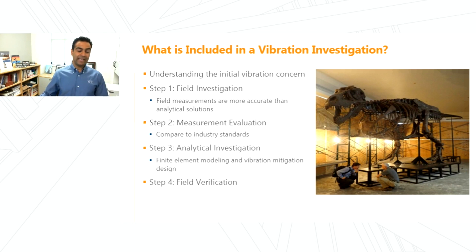And then finally, the field verification. As Rich described, this is not a strength problem. This is a serviceability problem. It's not well codified. So we usually try to do a final step, which is optional but highly recommended, to actually go out after a repair was implemented on the structure and verify that the measurements we are collecting agree with what we predicted, and that the structure or the floor is now in compliance with the applicable industry standards.